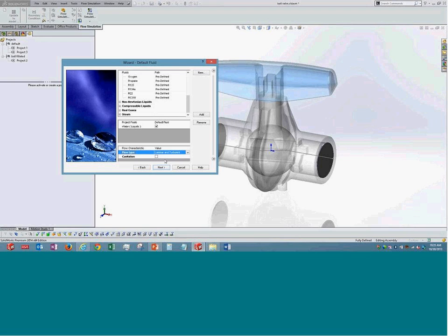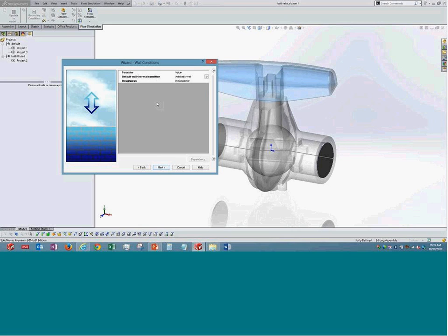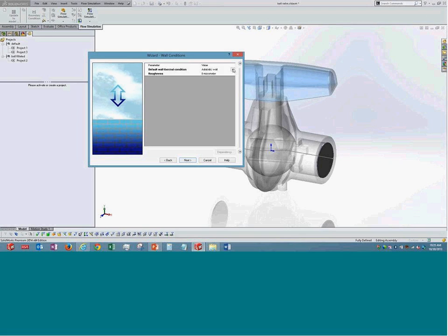We specify the roughness of the walls and initial conditions like what will be the initial pressure and temperature, and if it is a global system or external flow analysis, we can also specify velocity directions or velocity values. We can specify a few global turbulence parameters as well over here. There are these two kinds of parameter inputs that we can view.